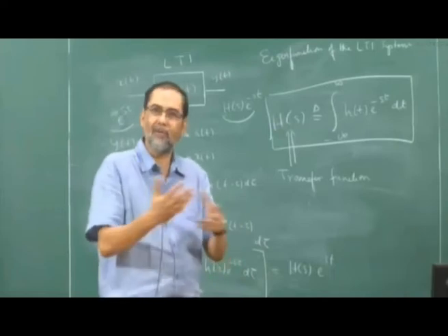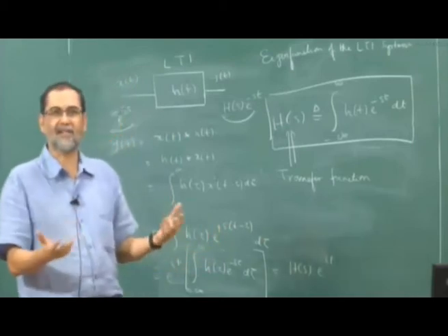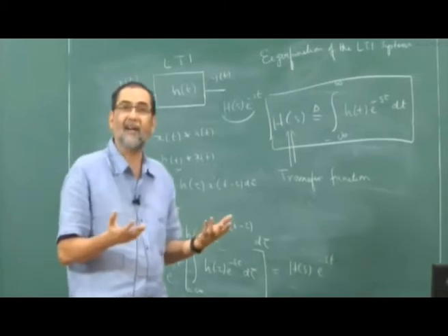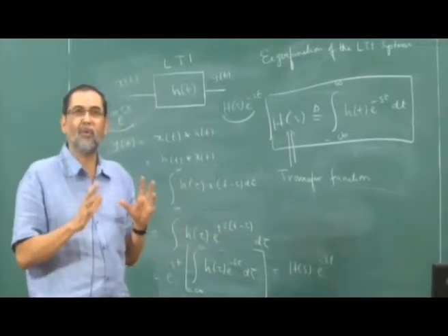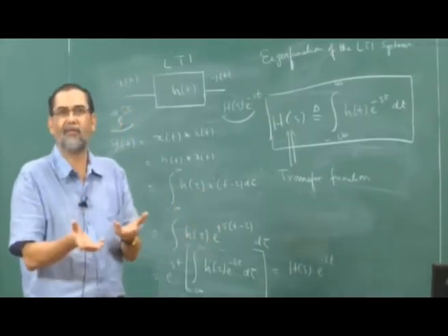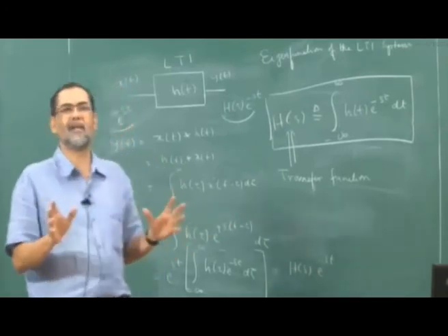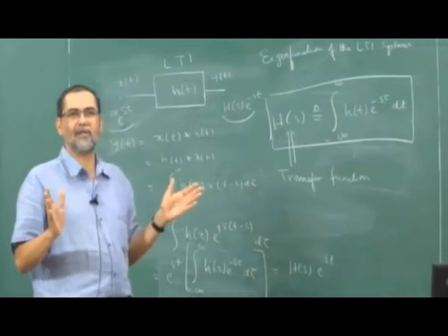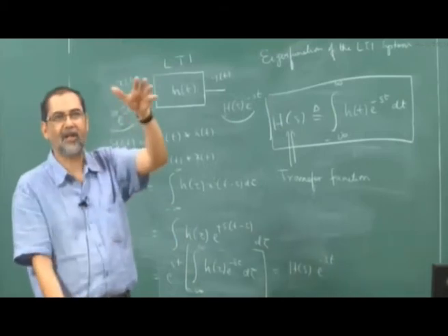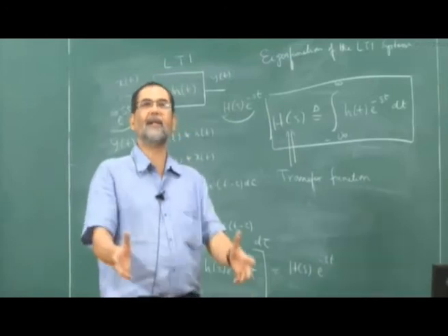The other way around, you have to see what is happening. If the frequencies are the same, is this LTI? You have to do more investigation. It may be that for that particular input the frequency is preserved, but for some other inputs it is not. LTI system says that no matter what the input frequency is, at the output you get the same frequency with some arbitrary change in the amplitude. If this property is preserved, then it is an LTI system.